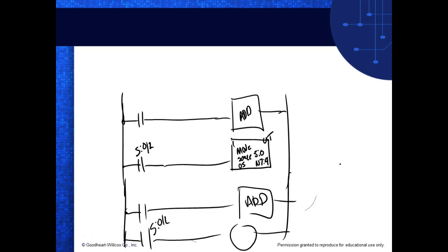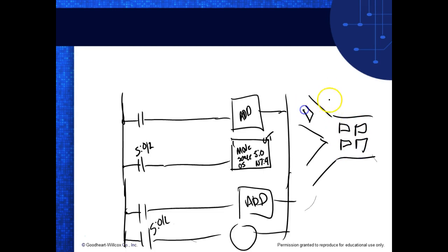The example they're using in the book is I'm feeding a main conveyor to 2 conveyors. What I'm trying to do is keep a total count. Well, when they get down here, it would be impossible to count them, right? Because they're side by side. But as they're coming in here, I could have a light sensor going across here. Every time this breaks it, this is going to take 1 counter.